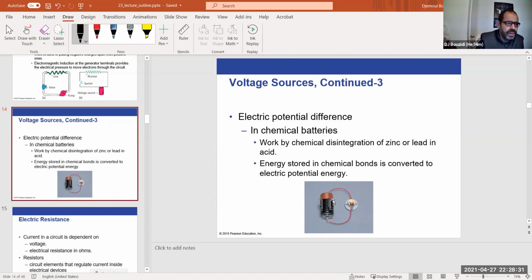With a battery holder. And the battery in here is going to provide the charges. Now, when the charges go through a resistor, like for example, the light bulb, they will cause it to heat. They will be moving through a filament of tungsten in here. That's the material that is used inside that element. There is power dissipated in the resistor proportional to the square of the current. So if the current is even a small value, it will cause a lot of power in here, and that power is the so-called Joule heating.